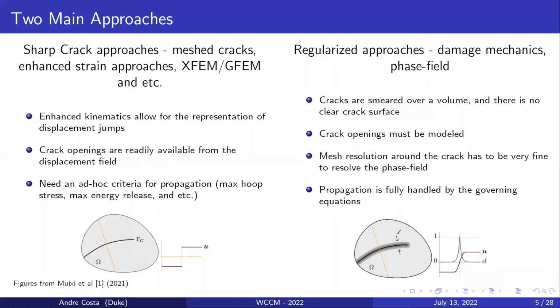The second approach involves the regularized methods, including damage mechanics and the phase field method. In these, the cracks are smeared over a volume and there is no clear crack surface. Specifically for hydraulic fracture, this is a considerable drawback because additional modeling has to be done to extract the aperture.